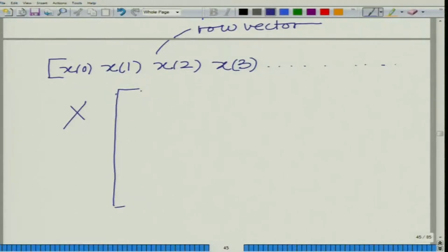So, now you can see, let us say the first column corresponds to C0. Now, we have x0, C0. Remember, C0 at time 0 is x0 plus x of minus 2. Now, we set x of minus 1 and x of minus 2 to 0, similar to what we have been doing, that is the previous bits before the starting of time at t equal to 0 are dummy bits set to 0.